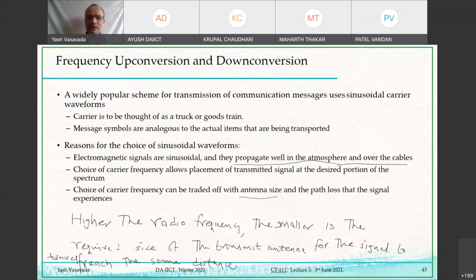It still has some frequencies. It's not that it's just a constant DC signal, obviously not, because you are going back and forth across different symbols, and so you are changing something. And whenever you are changing the signal, it cannot be a constant DC signal. So it is not a single frequency DC signal with exactly 0 Hertz of frequency. It has a certain spectral band, but that spectral band is centered around 0 Hertz. We'll shortly see a visual depiction of that.